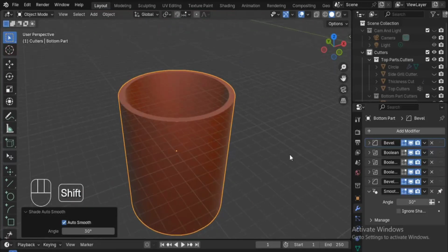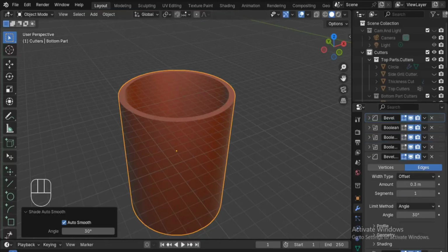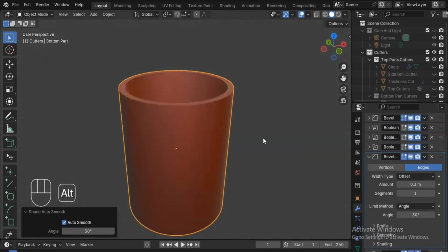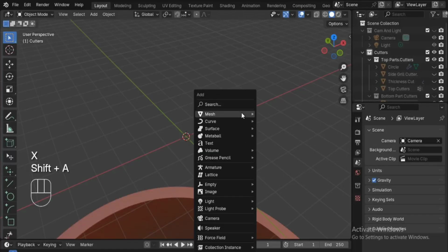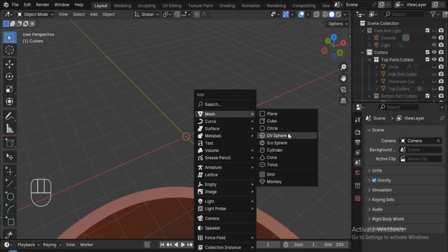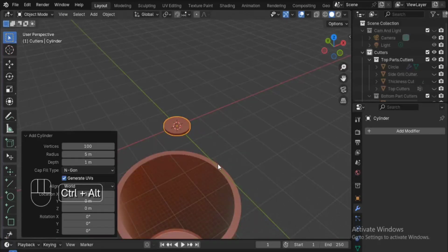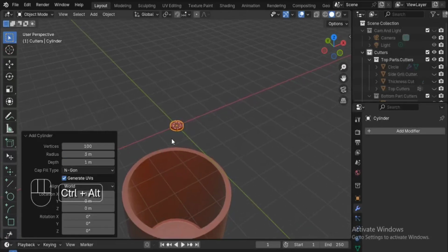You can search for shade auto smooth to reduce the amount of distortion that happens from incorrectly calculating the normals, and get rid of the abnormal problems of the normals. And obviously also always go to the bevel modifier, and the harden normals option should be checked in the normals panel in there as well. These two things have to be kept in mind if you're seeing that after doing booleans there is some geometry distortion going on.